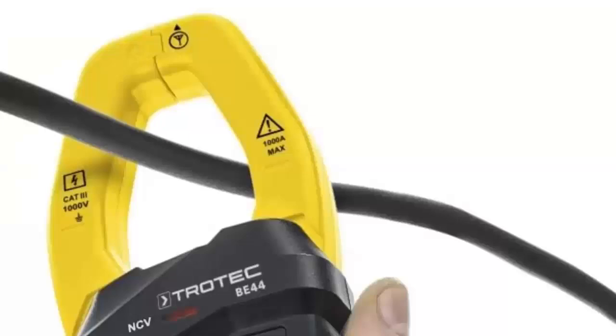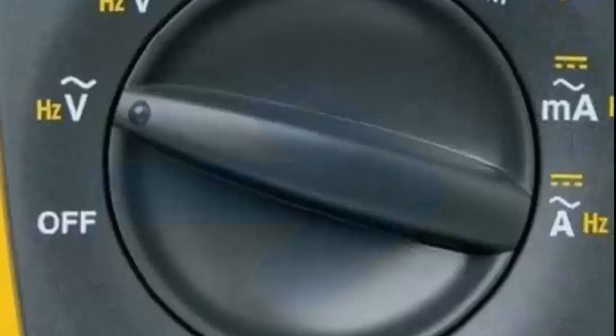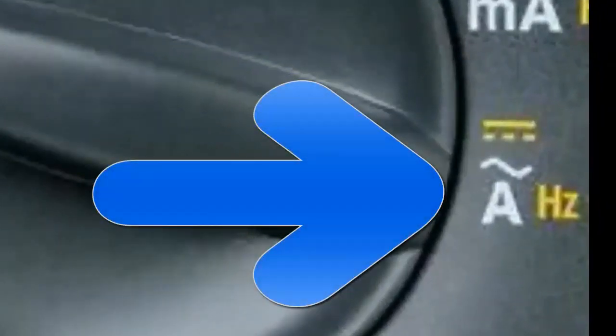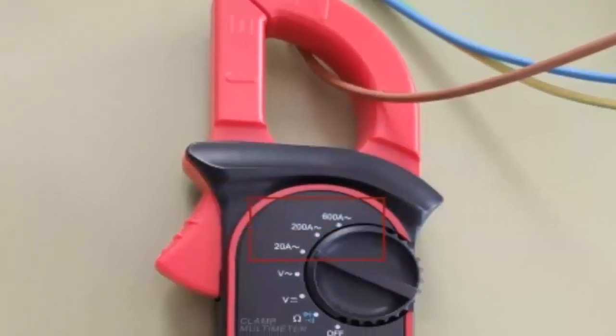2. Amperage measurement. To measure amperage, the digital multimeter must have a clamp meter function. Select the AC amperage option, place a single power cable inside the clamp ring, and measure the consumption. The measured value should be equal to or less than the equipment's nominal consumption, RLA.